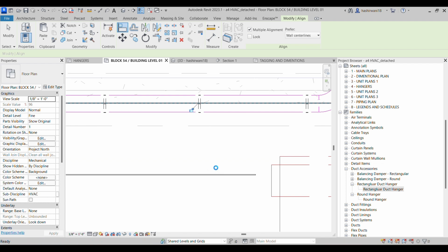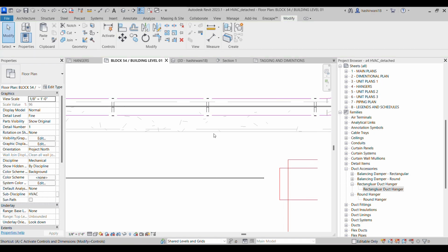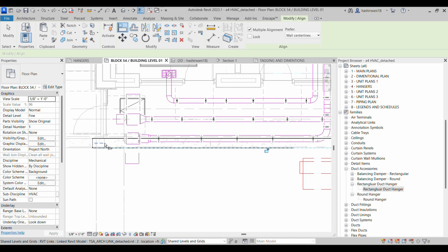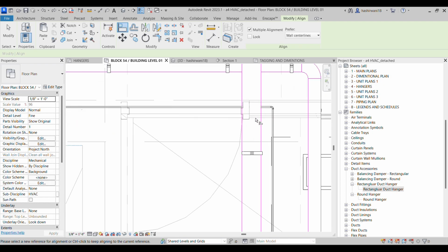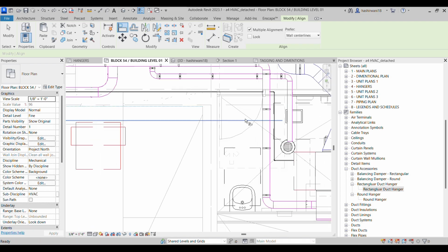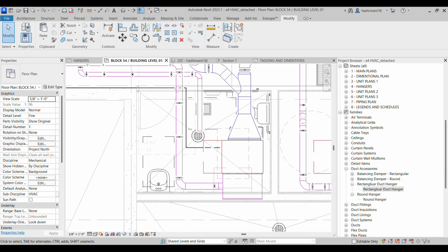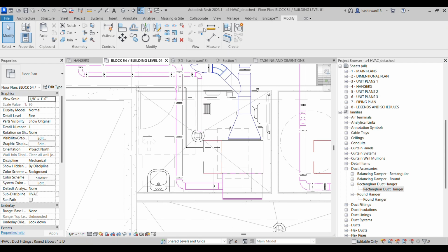Control Z it. Okay, and then escape. I'll simply select align option and then align this one to this. So now we can clamp it to this particular wall. Looks alright. Okay, and make sure it doesn't clash with anything else, right? Looks alright. Yeah, so like this, and then we go back to my Revit document, and then the other pipe comes here, right. So what we're going to be doing here is